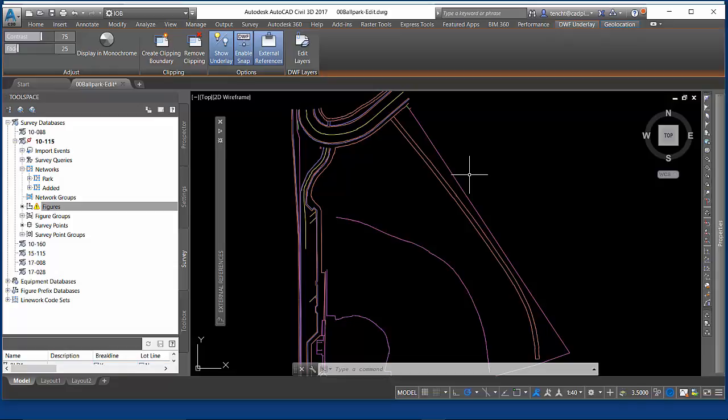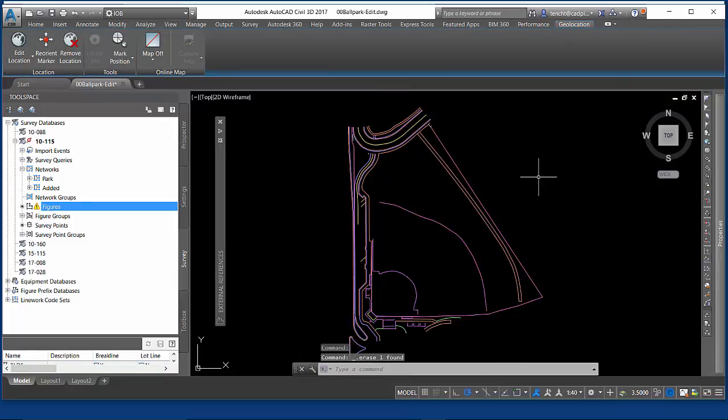They're all non-editable, pretty easy to clean up, produce a decent AutoCAD-level deliverable. Now if I want to go out to raw AutoCAD by itself and actually end up with something that's editable and manageable as a real AutoCAD drawing, I'm going to use either the export command or the export to AutoCAD command in Civil 3D to achieve that result.